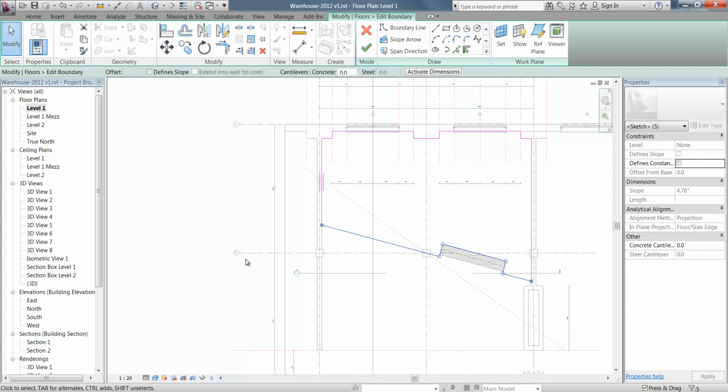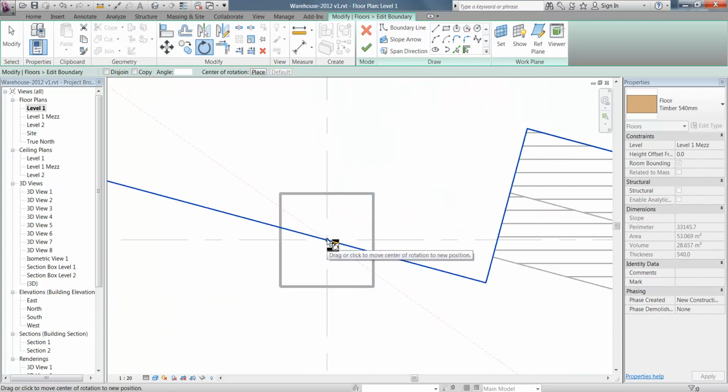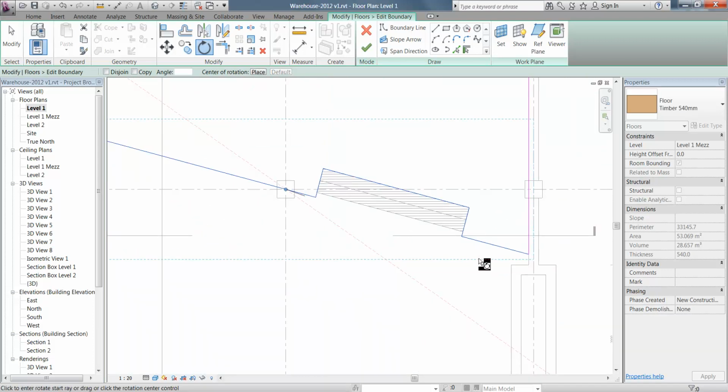That's right, exactly. So you've got that in most Autodesk programs, and so now again I can use rotate, just like I had earlier, and I can again make sure the base point is where I want it to be. It looks like it's on the right point anyway, but it doesn't hurt just to double check. And so again, I can use the edge here as my base angle. So you can see there's the line coming out from my base point, so I'm going to snap that onto this edge here, and now I can bring that around and it'll line up exactly with the reference point.